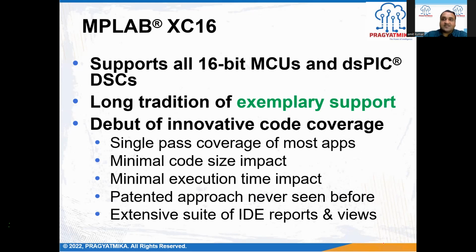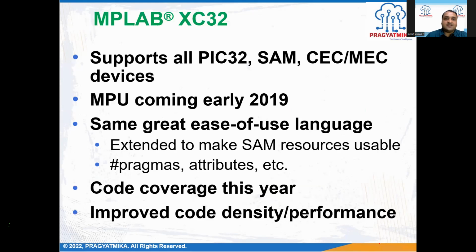In that case, XC16 comes to our help, and it reduces the code size through the compression feature and increases the code density. That is also very important, that whatever you write should go evenly into the memory of the microcontroller. That's where the code density enhancement is required. And whatever program we write should execute in real time. That's why minimal execution time impact is required for the XC16 compilers.